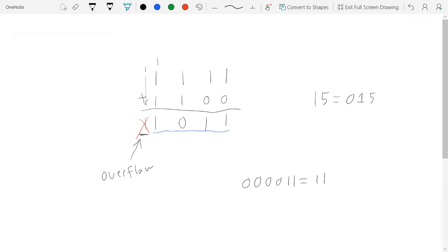So we've got this 4-bit addition going on, and I want to break this up into individual columns. We want to modularize this. I said we wanted to make a 1-bit adder circuit, and then we want to chain these together. So we want to modularize this into 1-bit addition.